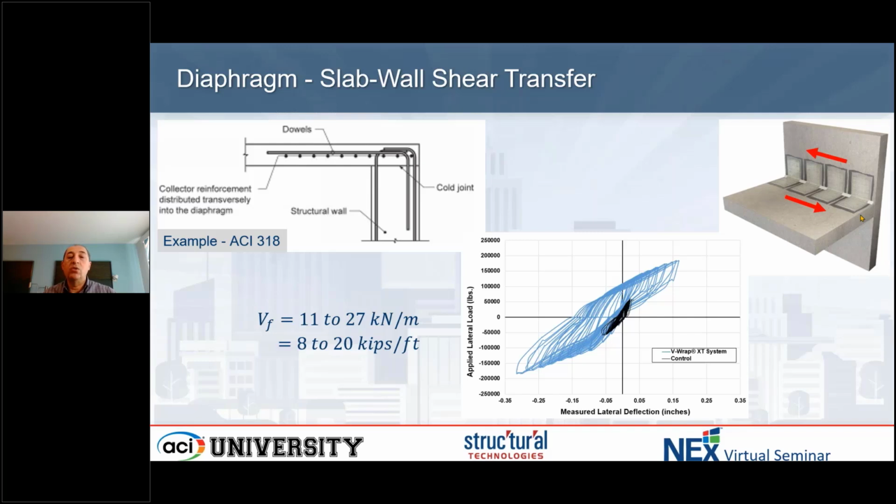The crack would generate along the interface through the concrete, and there'll be no load transfer. That is the black diagram in the middle, and you can see it's under lateral testing, dynamic loading, tension, compression. And then with FRP, you can see a significant increase in load transfer, allowing some movement. So there's some generated, I don't want to call it ductility because it's not really that much ductility, but you can see it's improved the behavior of the transfer of the loads.